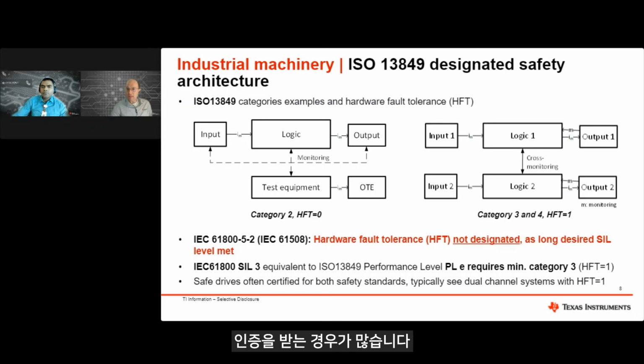What about the component FMEA? Let's have a look at a load switch example, which cuts power to the gate driver. The diagnostic, as shown here, periodically turns off the load switch very shortly and then monitors for faults, such as a switch remaining stuck on.